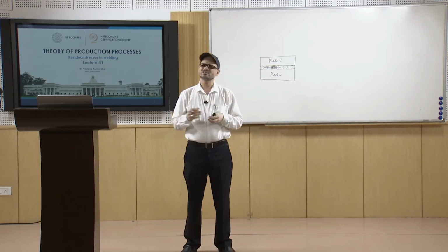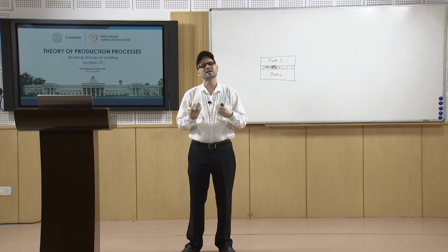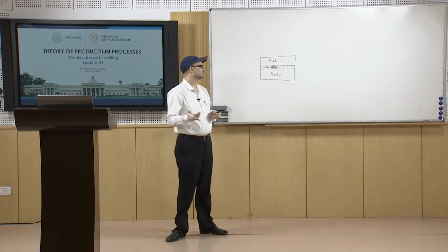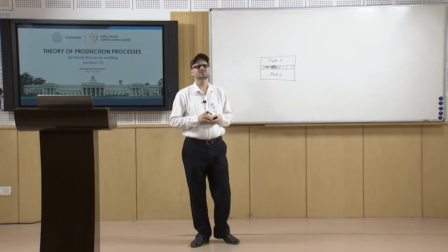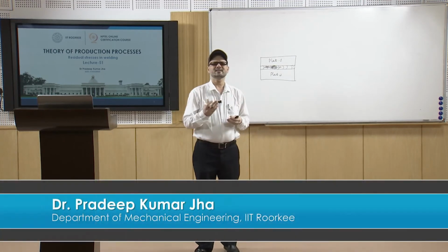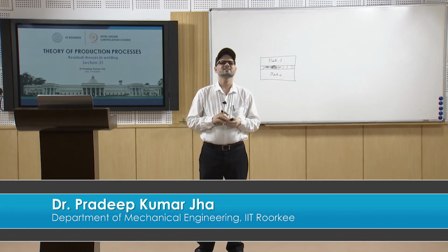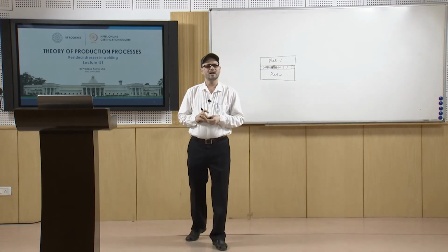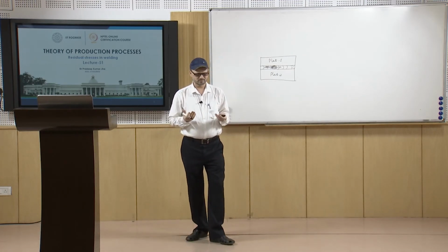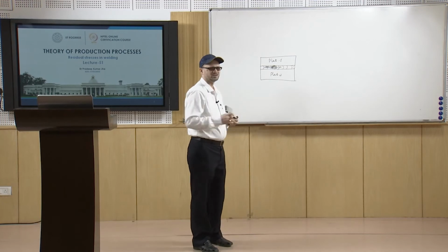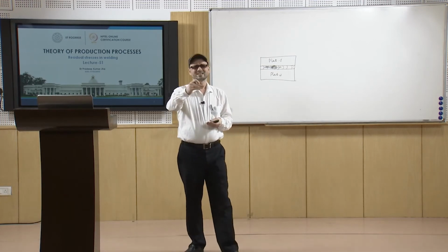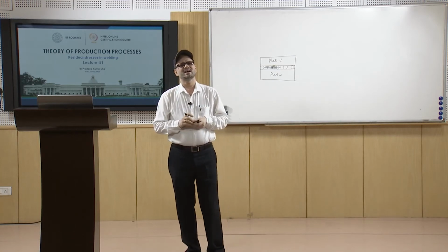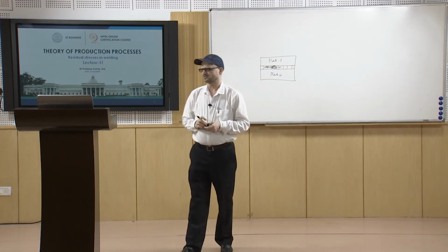But the stresses which are developed are known as metallurgical stresses. These residual stresses are not necessarily undesirable every time. They may be desirable also. If you take the example of metallurgical stresses, in certain cases it may be beneficial and in certain cases it may not. If the stress levels are too high, it may not be beneficial. Such stresses which are formed because of the phase transformation are known as the metallurgical stresses.